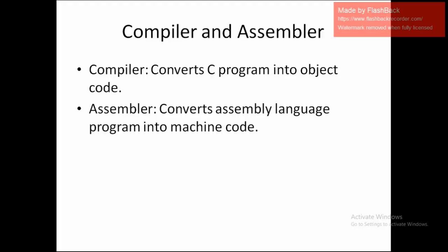And once the code is compiled, you can also do some more processing, such as you can simulate the outputs and see what sort of outputs you have derived from the coding. So for that, in the Keil software, you can change it to debug mode. That is the next mode, from editor mode to debug mode.